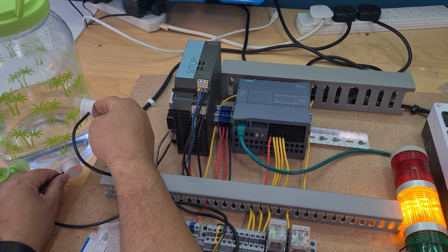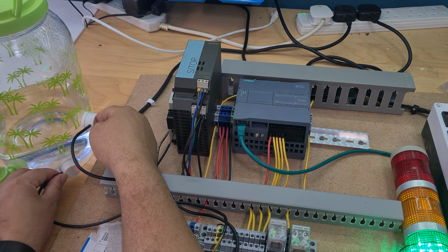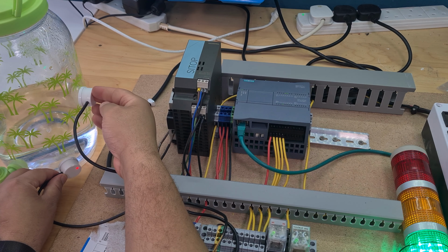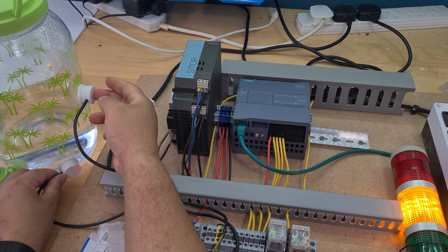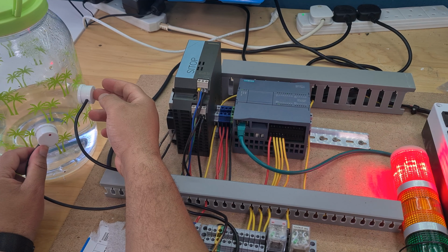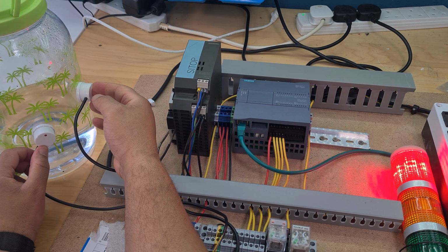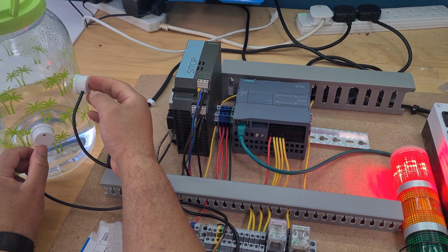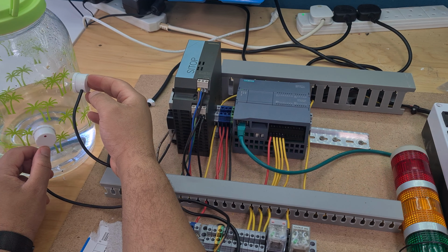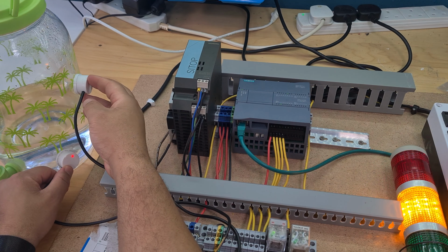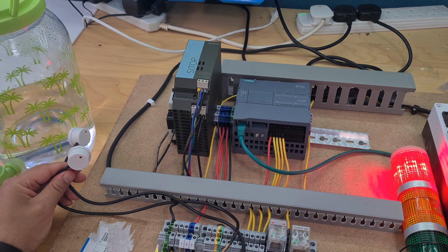If I bring this high level down to the water, you can see that I get a green. If it's then above the water, I get a yellow. And if the low level has no water as well, I then get a red. And in this instance, what I've done is, if the difference between these two is too fast, it's actually a very clever program.